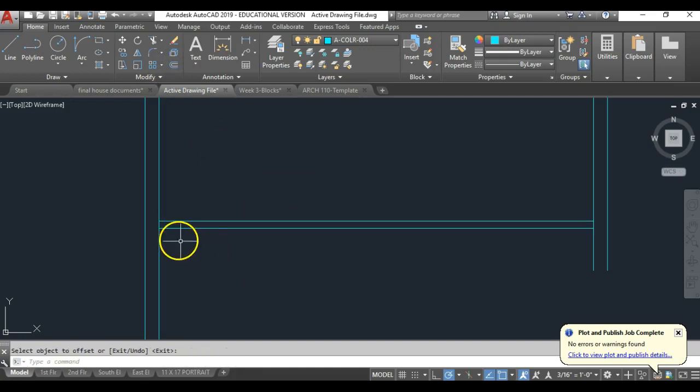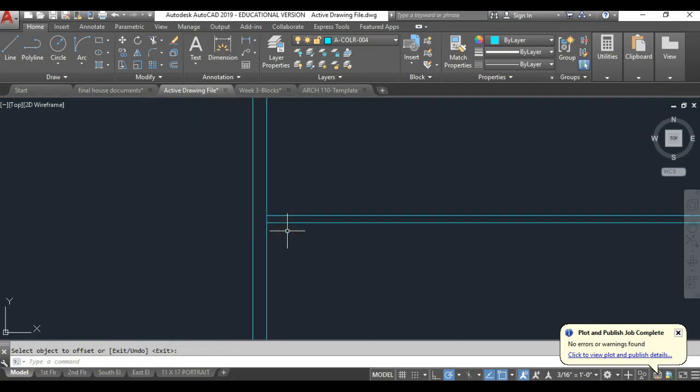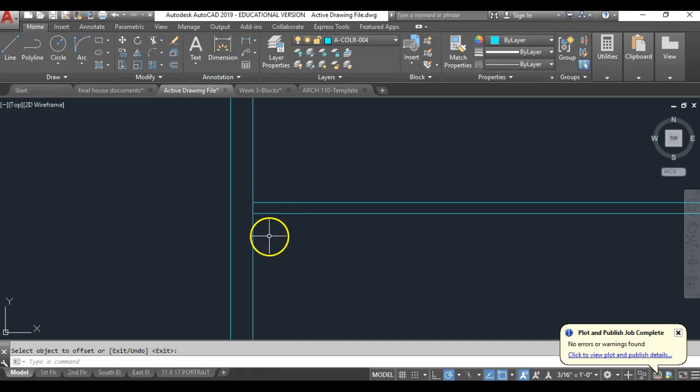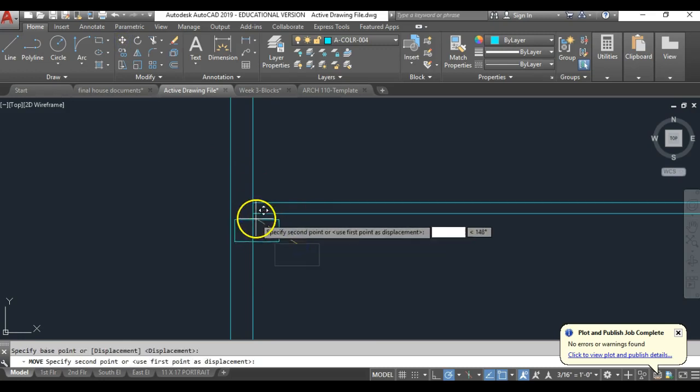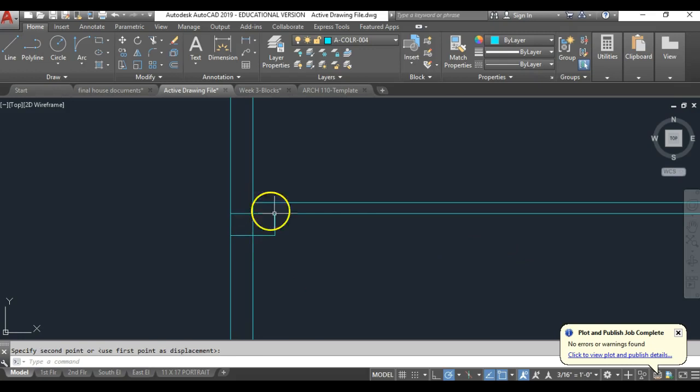And we have to start to design our footing. I think the footing is 8 inches deep by 1'4" across, a line at the bottom of this zone here. So I'm going to start by drawing that rectangle. Again, it's 1'4" by 8 inches down, and by 1'4", and then up and close that rectangle. And I'm going to go to my move tool and hit enter. I'm going to start by moving it up to that point there. So now it's not set left to right, but it's set up to down.